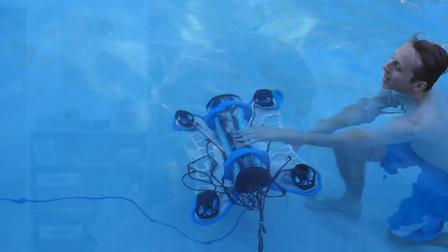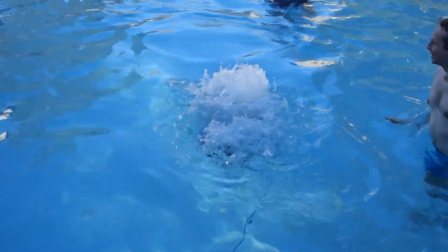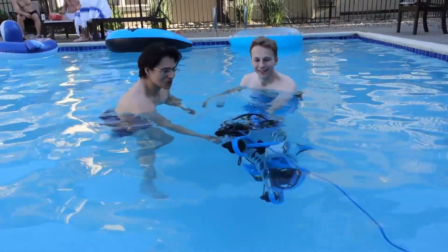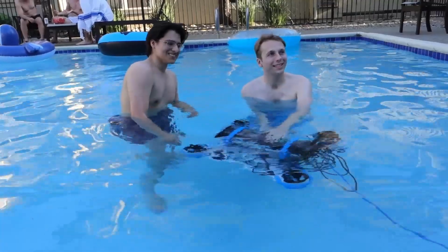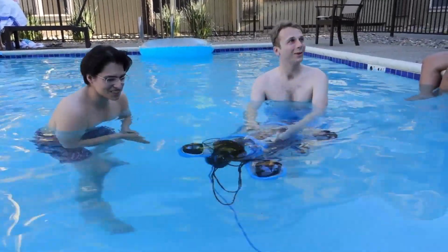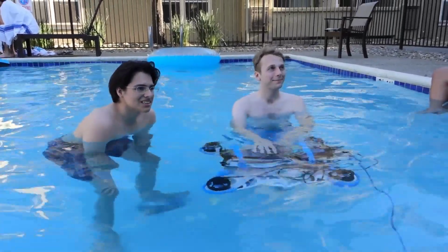Our submarine model is only useful if the performance of the digital twin accurately reflects the real system. To this end, Simulink's parameter estimation tool was indispensable. The three most important parameters for a plant model are the inertia matrix, the hydrodynamic added mass matrix, and the drag coefficient matrix. For complicated systems like our robot, these values are very difficult to determine analytically. Fortunately, the parameter estimation tool allowed us to take real sensor and motor command data our team collected during pool testing and perform a least squares estimate of these unknown parameters that map motor commands to vehicle dynamics.